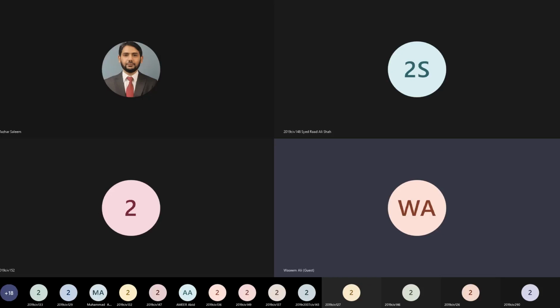So the large scale reading is 1.2, and then on the small scale, if you read in the counterclockwise direction, the reading is 85. The reading is 85, and 85 will be multiplied with the least count 0.001, and ultimately you will get 1.285 millimeters. Is everybody clear about this? Yes, sir. Okay. All right, so we have seen how to read the extensometer.